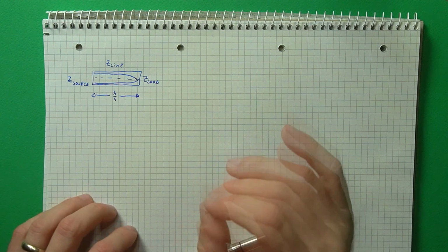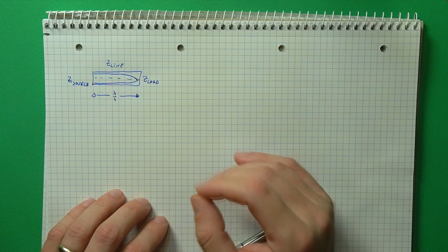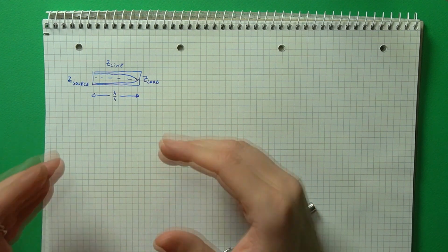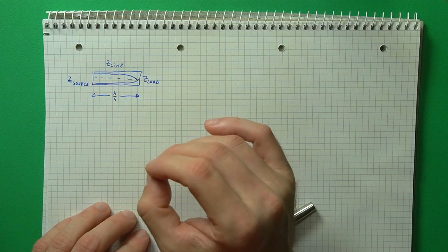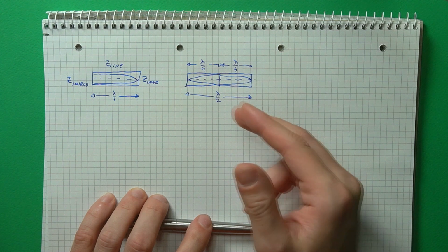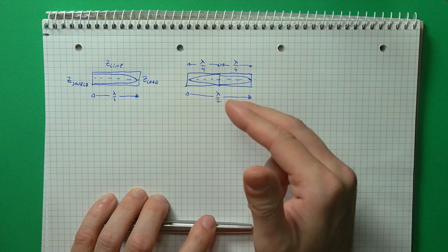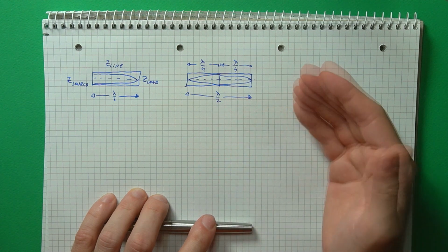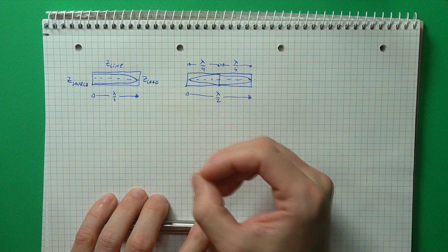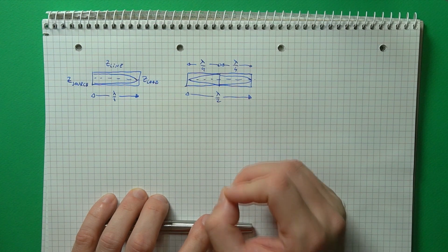The reason for this has to do again with the condition needed to fulfill the requirement that the line needs to invert the signal that is passing through it. We saw this occurs for a line that has a length of a quarter wavelength. But you may also notice that if the line is half a wavelength, so 2 times quarter wavelength, then the reflected signal ends up being phase shifted by 360 degrees, so it becomes in phase with the incident signal at the beginning of the line. In other words, that doesn't really help us.